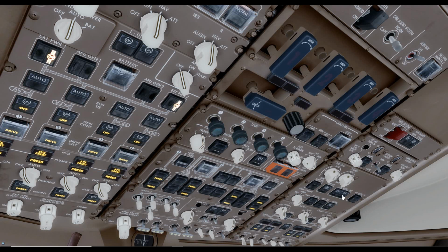We then go to the aft part of the first officer's side of the panel. Passenger oxygen should be guarded in the normal position so that the system can automatically deploy the oxygen masks in the cabin should a depressurization be detected. Yaw dampers should be selected on, and then we're looking at the cabin altitude panel,